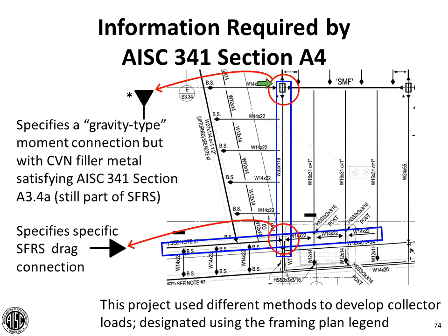So here is an example of how the connections that relate to the seismic force resisting system might be indicated. Again, a fabricator looking at a gravity cantilever beam, or a beam that, for reasons of deflection control, for example, the engineer decided he or she wanted to make a moment connection, would not have a very easy time trying to differentiate that from a seismic connection unless the engineer makes it explicit.